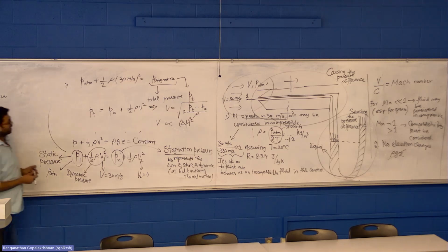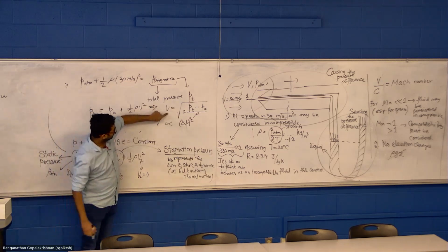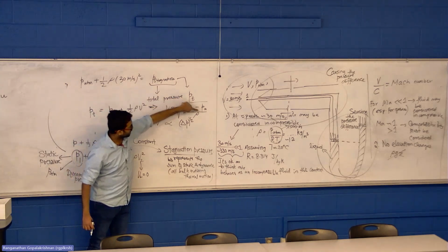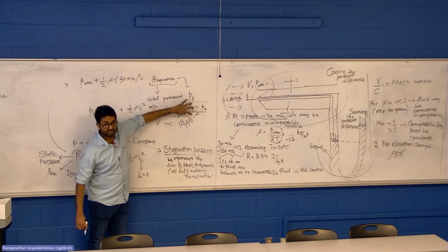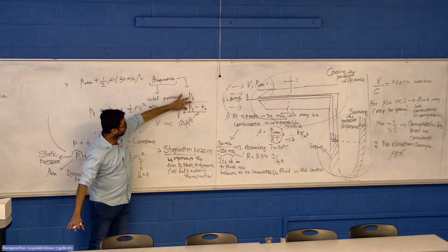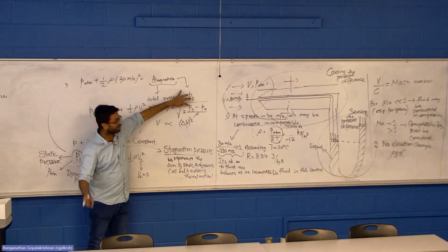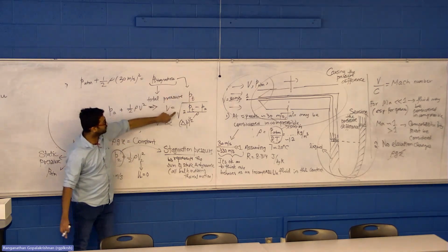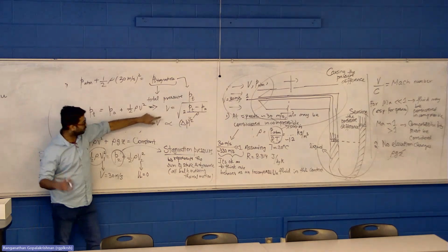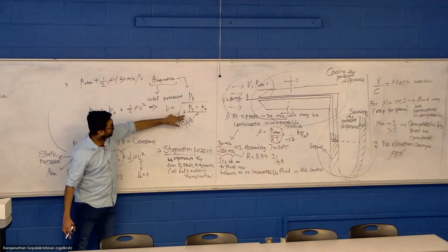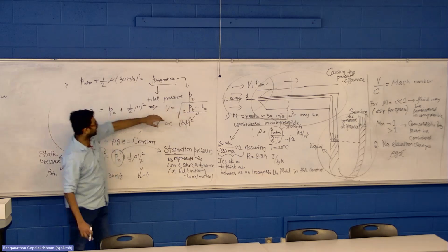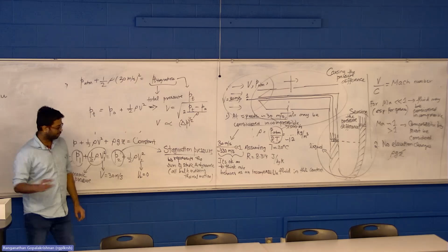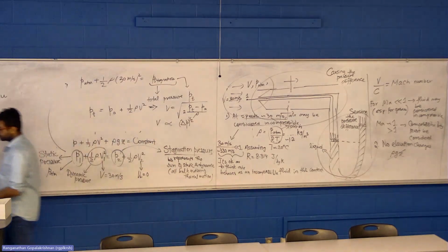Good. Okay, so we have this velocity equal to 2 times square root of Pt minus Pa divided by density. All right. Now, if you know Pt and Pa, you can compute a difference. Or if you are able to measure the difference directly, you can use this equation to compute the delta P, because in our case, we know velocity, we are asked to calculate something else. So let me write a few notes here for you to remember.